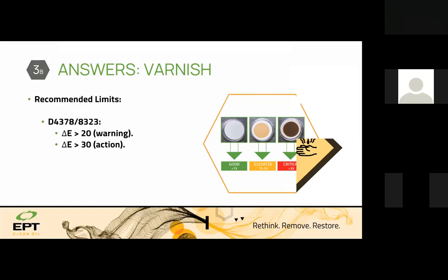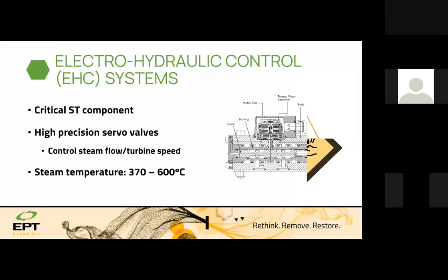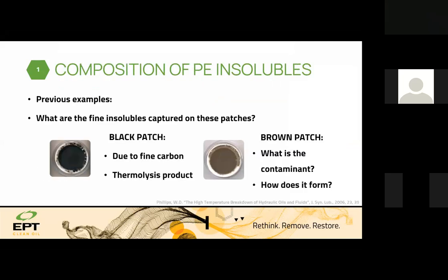The best is to keep the oil always with an MPC below 5, so not allowing those oxidation molecules to stay in the system. So start to remove it from the start of the life cycle, from when we put the lubricant in the system, with a varnish removal system which can remove the soluble varnish or soluble oxidation material. This is the best.